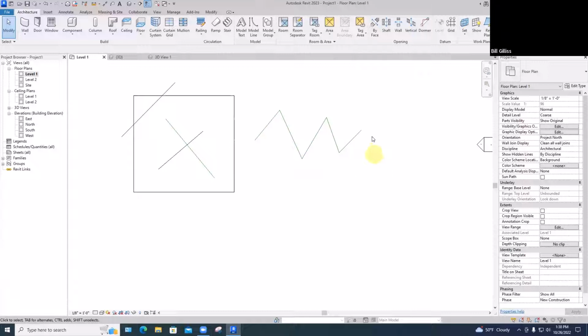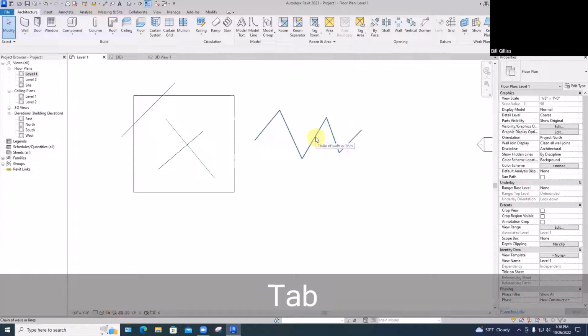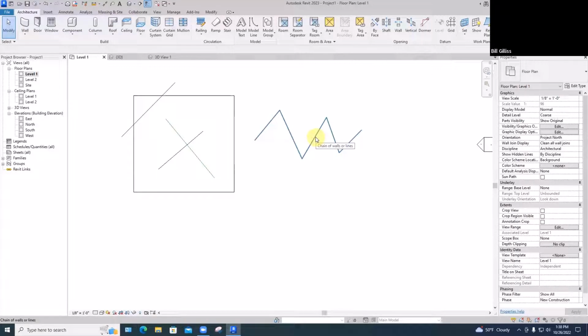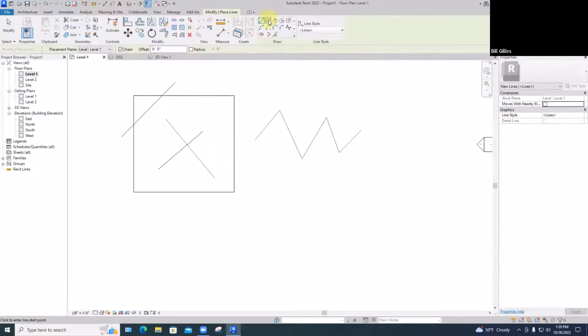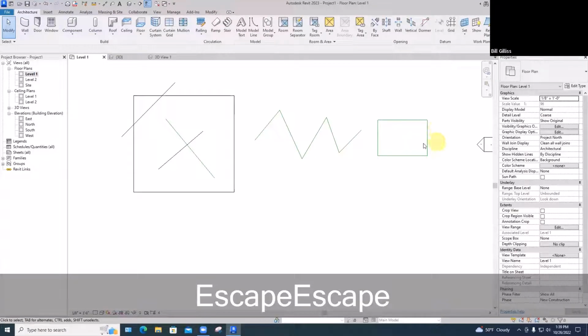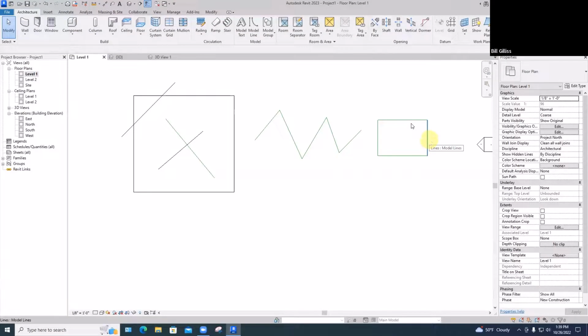If you want to select all these at one time, things that connect corner to corner, if you hover over any one of them and hit the Tab key, Revit will look for everything that's connected end to end of that same type, only ones that are touching. And we'll get into selection methods later on. Rectangles, as you know. Unlike AutoCAD, Revit doesn't have the ability to specify a second point directly using the syntax with at, like at 12 feet, 8 feet. The idea is you get close, and then let's say I wanted this side to be an even 9 feet. I'd select this one.